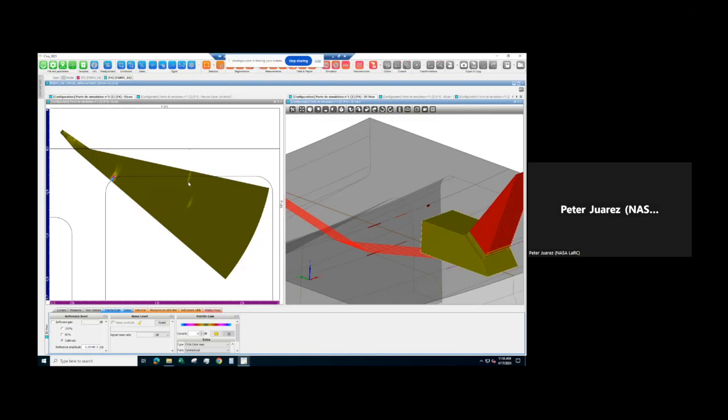And so we get instances where a lot of these defects are as close to the noise floor as we can imagine, to the point where I would not say confidently I'd be able to find these in the field because of how much the signal quality went down. And we simulated up to like 1 millimeter layer of adhesive, and the results are just as bad as you can imagine for that. And so with this, we were able to bring evidence to the people that were in charge that in no uncertain terms, you need to remove as much adhesive as possible if you want to have a quality inspection.